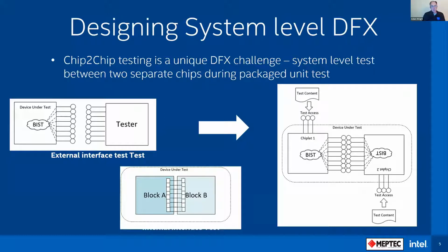Now, whether or not we touch each of those pins at HBM is up to the cost profile of the product, but we can get to them all, right? So if I need to figure out what's wrong, I can go on a bench, I can go on a tester, and I can go look at those pins. And there is a huge amount of analog BIST out there that we use in order to validate our IOs. From a logic point of view, internally on the chip, we have X test, right? So we are able to do a boundary scan test between block A and block B to figure out, do we have a good logical connection? Again, you can do that at speed. And these are both known approaches to how we handle these things.